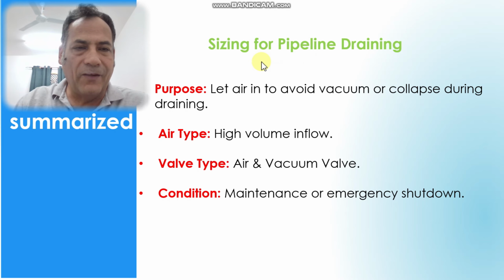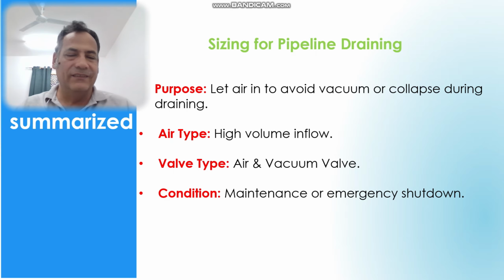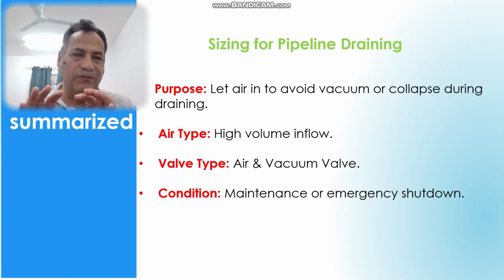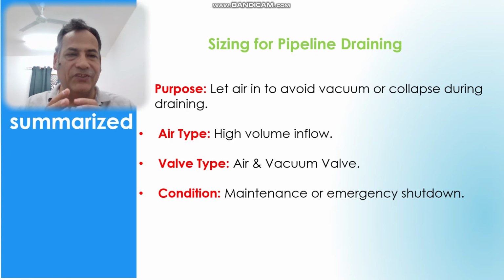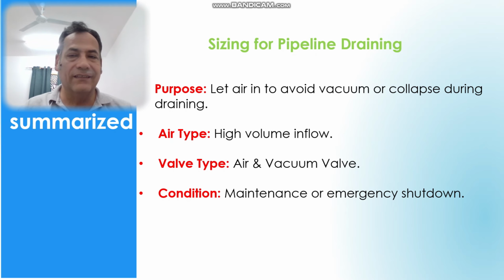Sizing of the orifice during draining of the pipeline. What is the purpose? Let air in to avoid vacuum or collapse during draining. During draining, behind the water a vacuum will be created, and this vacuum is very dangerous and can collapse the pipe.